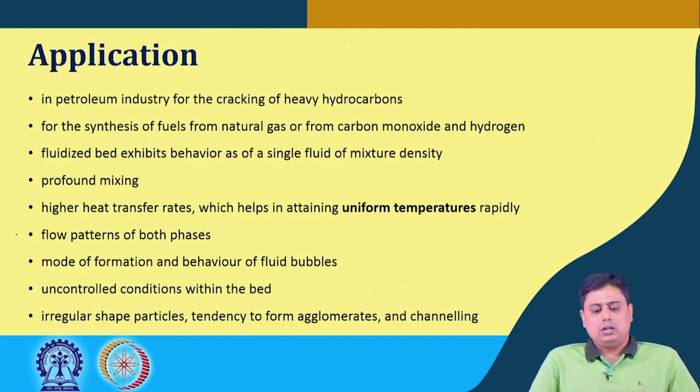But to use fluidization or a fluidized bed, we need to know the flow pattern of both the phases. We need to know the mode of formation and behavior of fluid bubbles, because these are particularly relevant for the gas-liquid system, and they become more and more prominent with a higher gas velocity, because in several applications you need higher throughput that can be achieved by a higher flow rate of the gaseous phase, and also a dense, high-density fluidized bed.